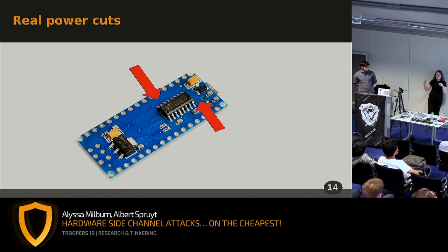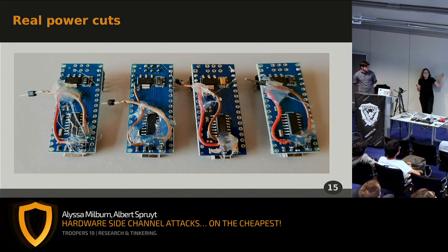And the power that it's using, you don't want to mess with. So you actually have to make cuts in 2 places to preserve the power, do a bit of soldering. And in real life, I think the most difficult part, at least for me, about doing side channel analysis is this, is getting things soldered and quickly piling on hot glue.